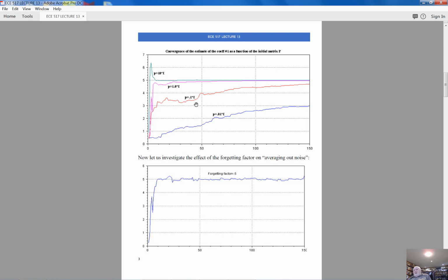And I made a statement that this positive constant, here it is 10, here it is 1, here it is 0.1 and 0.01, works as a constant gain in a simple control system, as a constant gain in the feedback. If this constant gain in the feedback is large, we're getting very fast convergence, a very short settling time if you prefer control terminology, and the high overshoot.